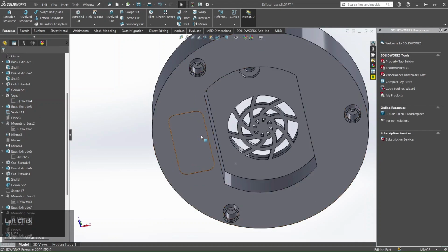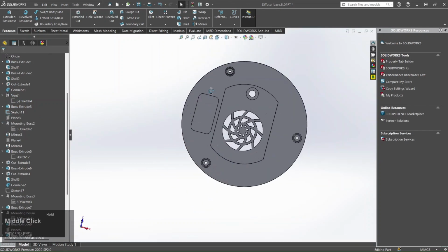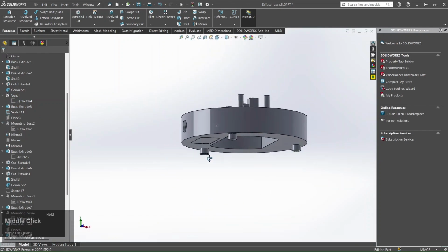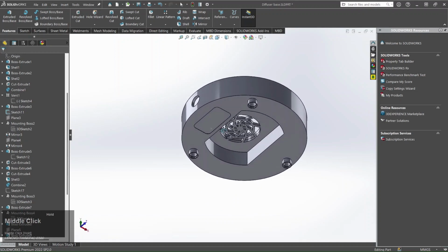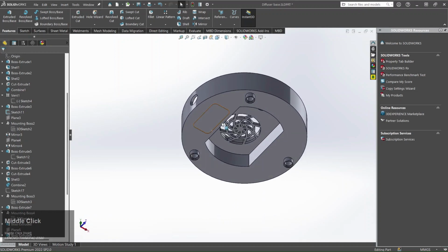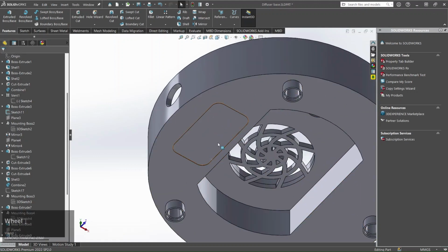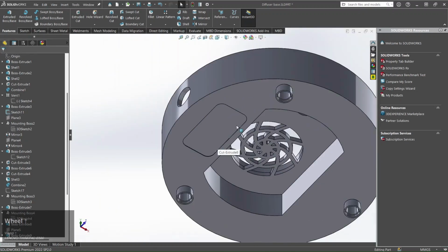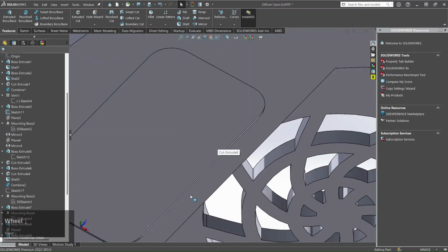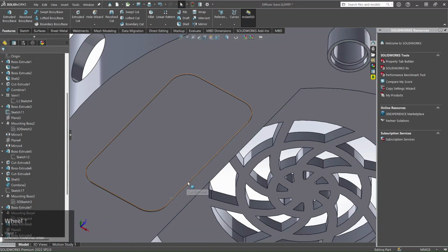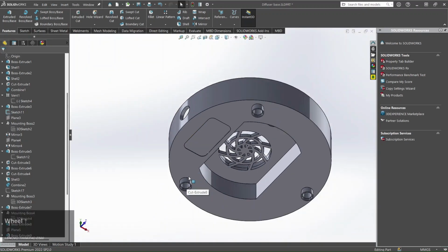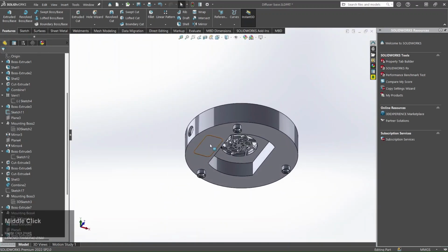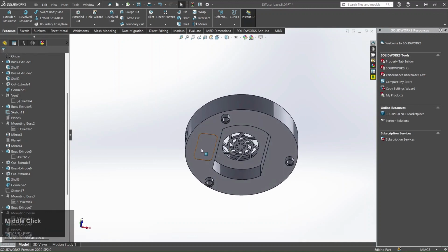So this is where maybe you put a company logo. You can put information about the power rating and all that stuff. So there will be some sort of sticker over here for that. That's why I just extrude cut this one by a small depth of 0.2 mm, because there will be a sticker sort of, so it will come over here.